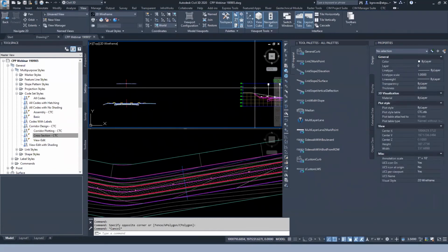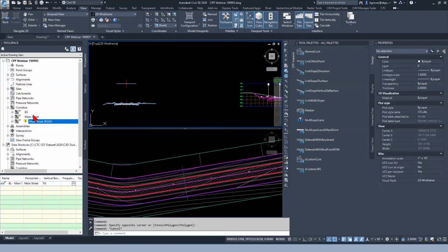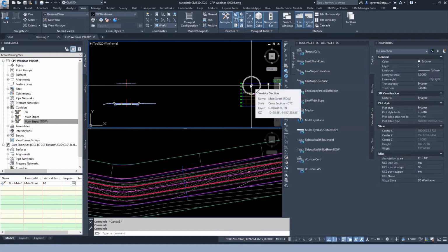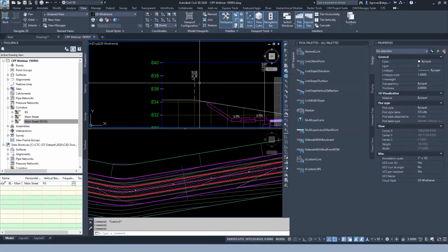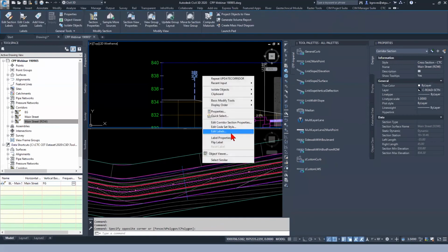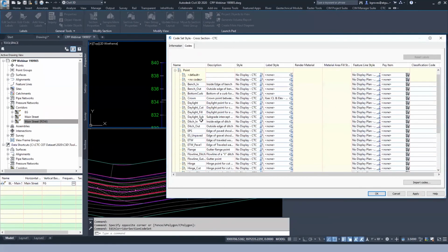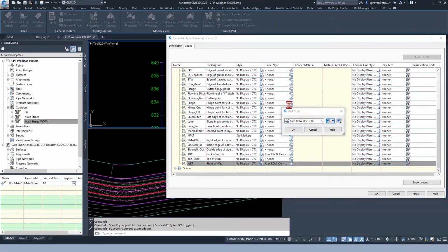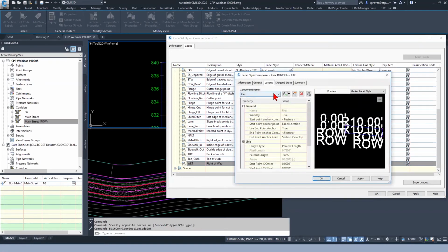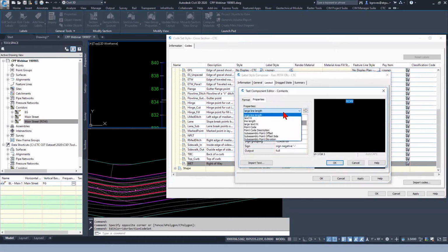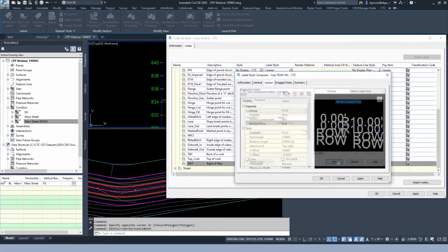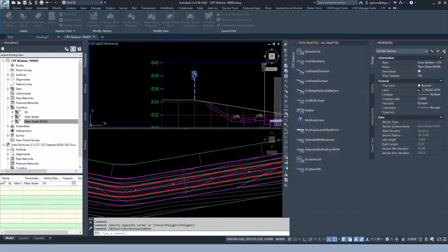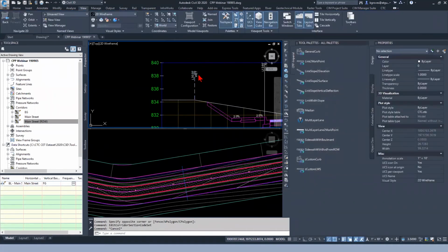And pay attention to right here on my screen, as soon as my corridor rebuilds, that code is going to populate. And now technically I have that specific label hard-coded to display the verbiage of right-of-way. So you'd also have to make sure that your label is set up to be either flexible enough or have a specific one. Do the actual point code as well, and that would make it the most flexible. Now it's going to say wetland, so I can change that everywhere else.